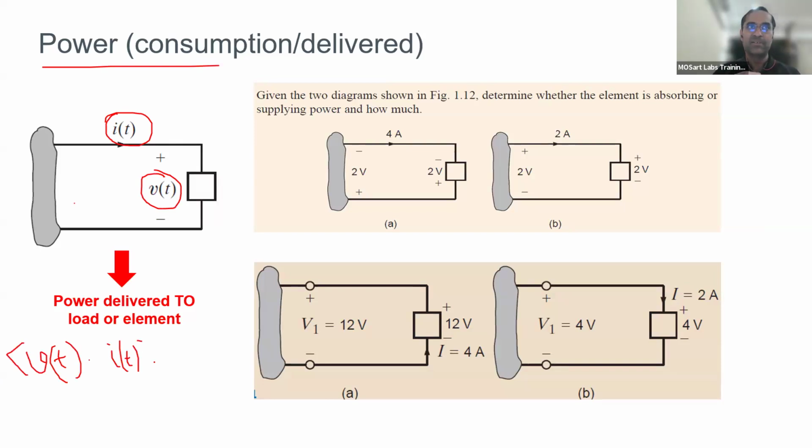You can take an average power, which means over a period of time, what is my power, the total amount that you are taking out from the battery. What is your average power consumption across the time? So you take an average across this. It is an average of all the instantaneous V of t into I of t. Multiply at different points, multiply all of that. Now you take an average. That is your average power consumption. But ultimately, power is voltage into current.